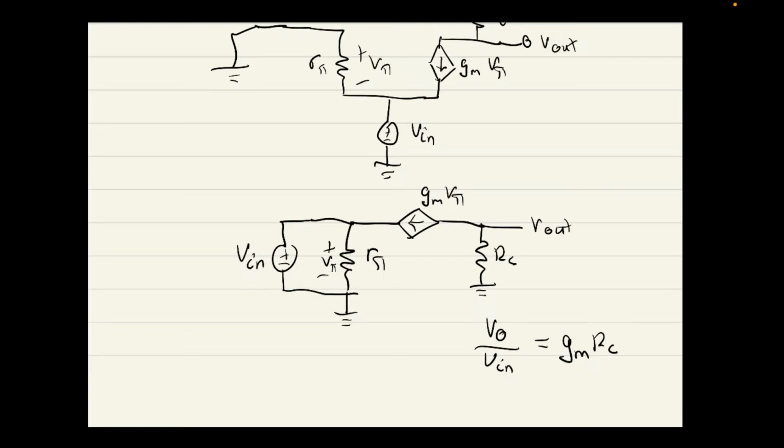So if you had, which we might see in the crash course in a different question or in the exam, a 2-stage amplifier, the small signal model for that, like I said before, is pretty big. But you can turn it into a 2-stage, right? So you can just find the gain for the first amplifier using the known equations and the input resistance of the second amplifier. Then you find the gain of the second amplifier, multiply those together, and you don't need to go into a small signal model, which probably will save you a lot of time in the exam. And that's why that doc's been made.